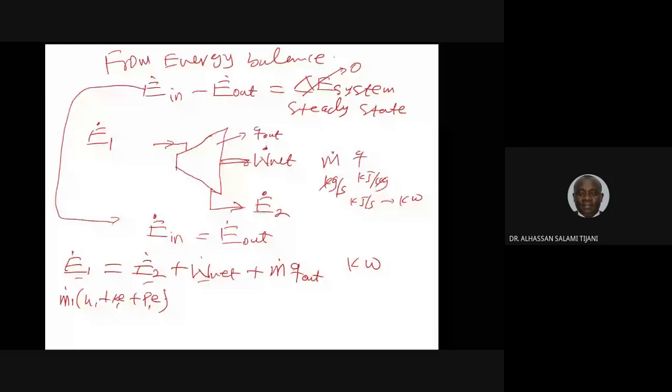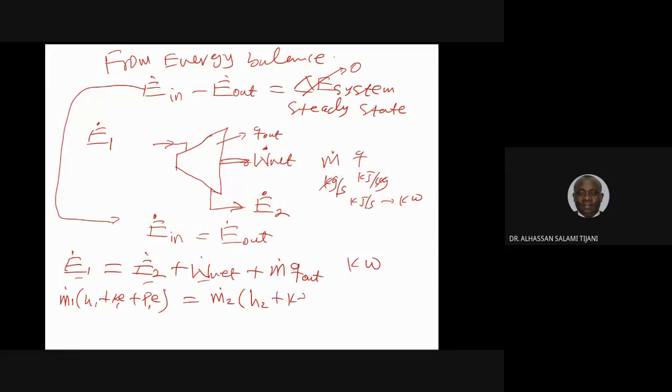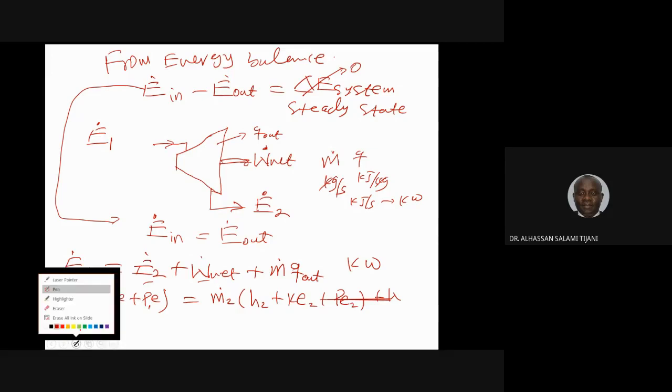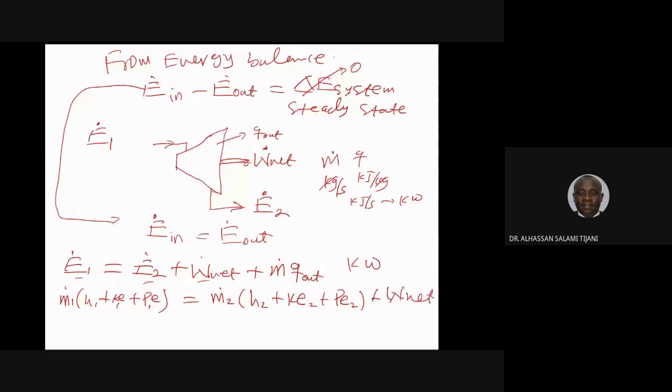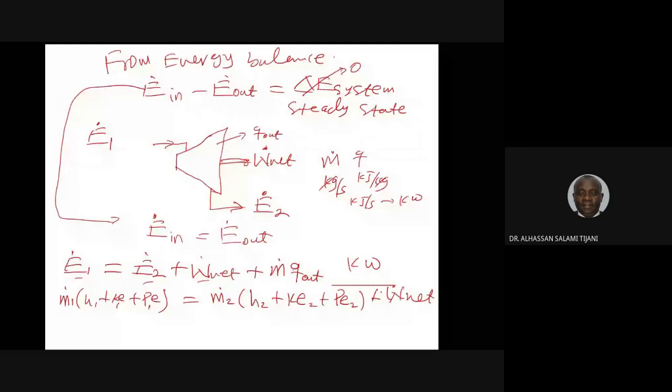This should be equal to M2 times the bracket: H2 plus the kinetic energy terms plus potential energy, and then finally plus W net, and then plus mass flow rate times Q out.